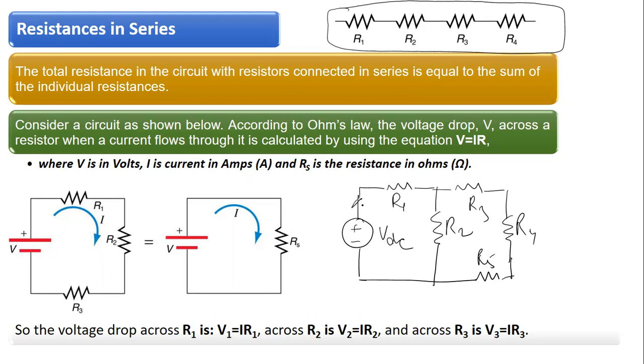Now, when the current starts flowing from this particular source, it would reach this junction. I hope what a junction is is clear to you. A junction is a point in electrical circuits where three or more branches are connected. So we have three branches here, 1, 2, and 3. So this current would divide into this branch and this branch depending upon the branch resistance, right? Now this current will flow through R3. The same current would flow through R4, the same current will flow through R5, and from here another current is coming.